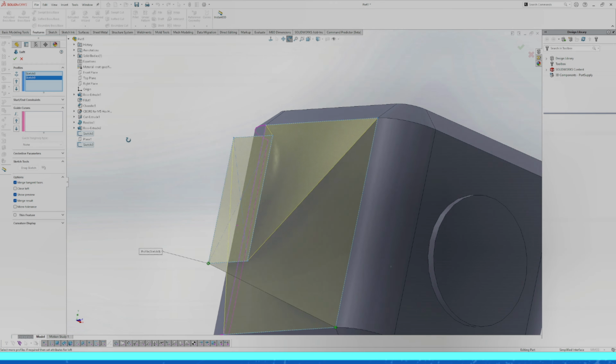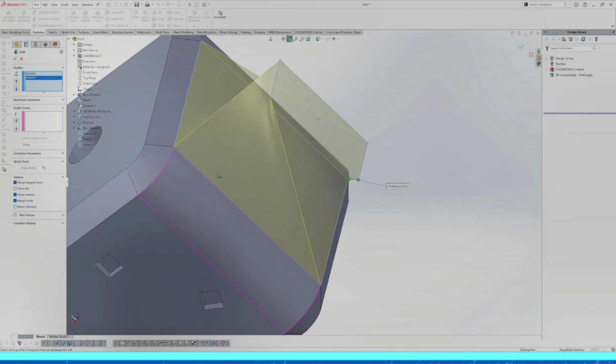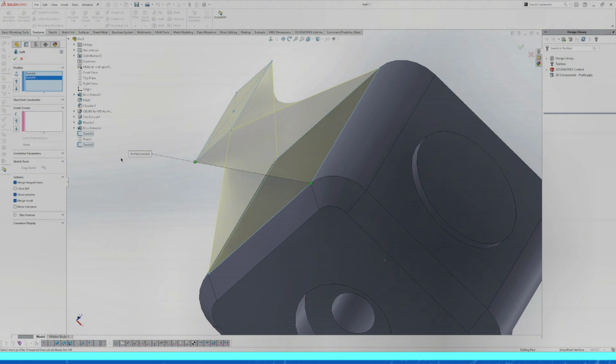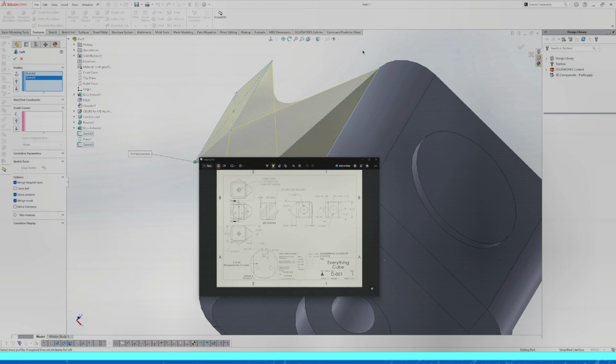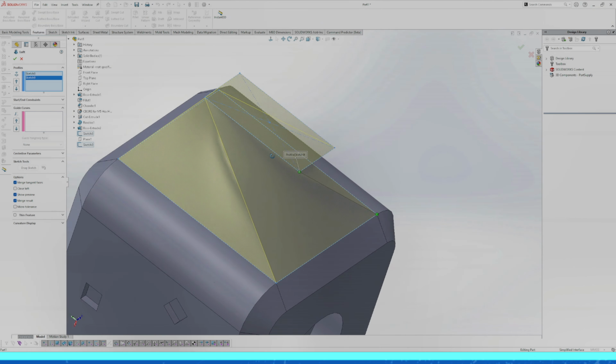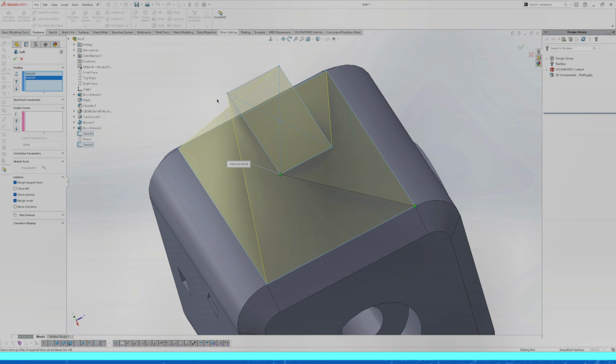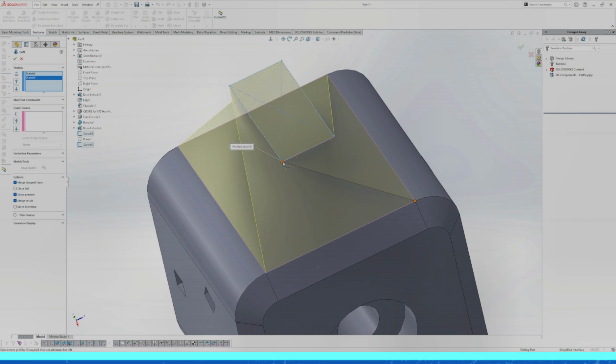And you'll see the 3D preview it's making is not quite what we want. It is actually turning at 90 degrees. And in our technical doc, it looks like it is not. So in order to fix that, we just need to move our reference points. So you'll notice there's a green point here, and these define which your references are.